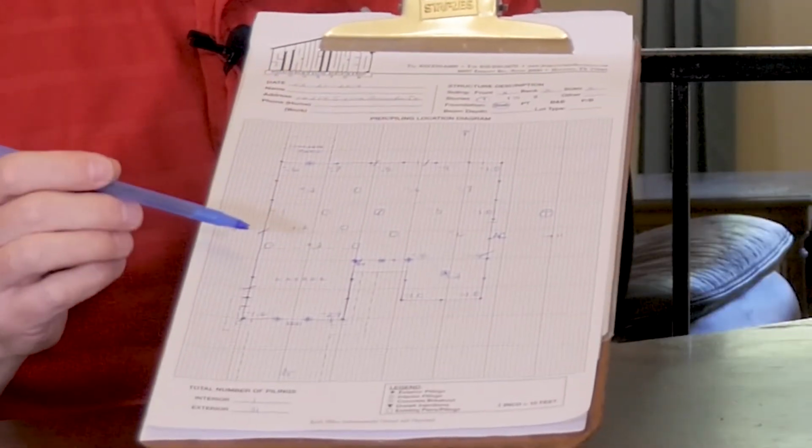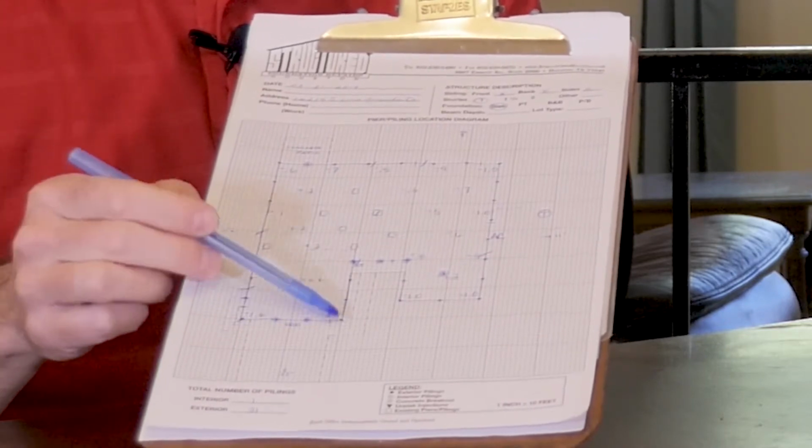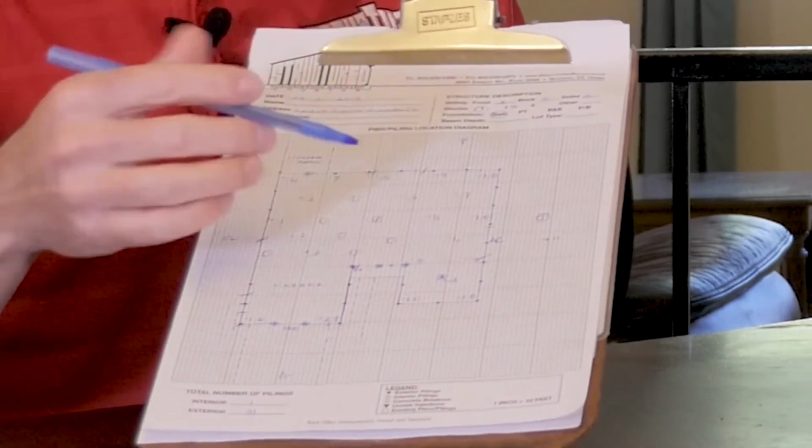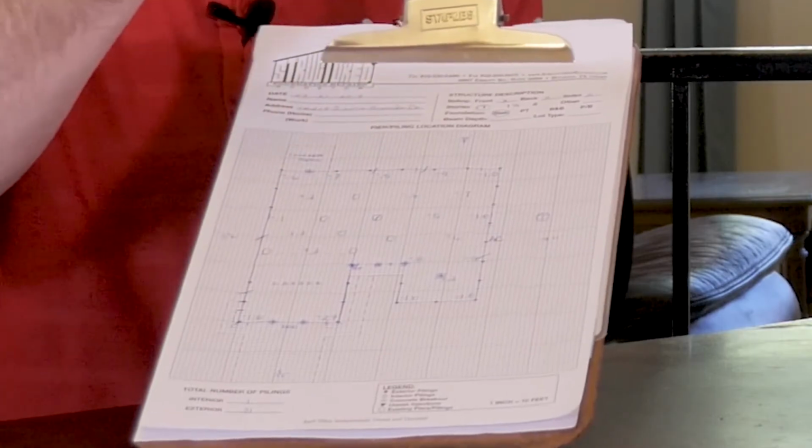It just gives us a base so that we can put a hand jack then on top of the pier. And then what the crew chiefs do is they'll line their crew guys up in these holes and assign, manning a hand jack, and they'll assign each crew member manning a hand jack a number or a number of times to lift on the jack. And then they count 1, 2, 3, and those guys pump those jacks to whatever count they're assigned, and then they stop and they lift the house in the process.